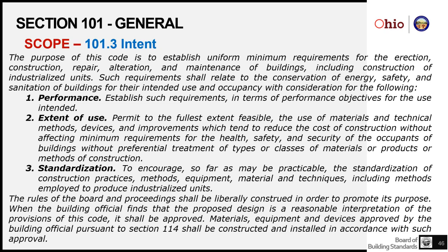If you sell other things in that marketplace, you can sell up to, but not past, 50% of your income from that retail can come from things other than what you grew or raised in a typical year on your property. As soon as you cross that 50% line by bringing in other products that you are selling, you are now a change of occupancy, according to exception number 3.